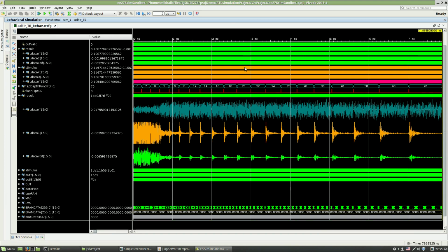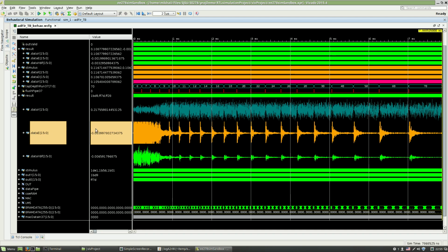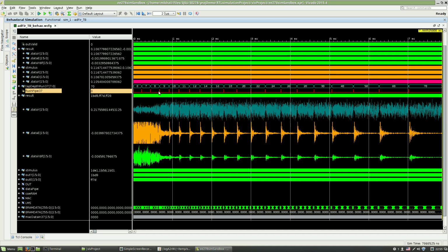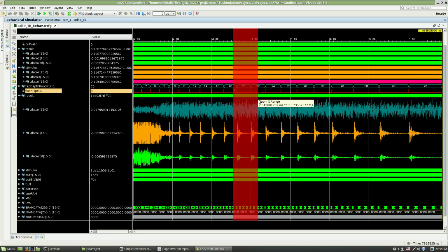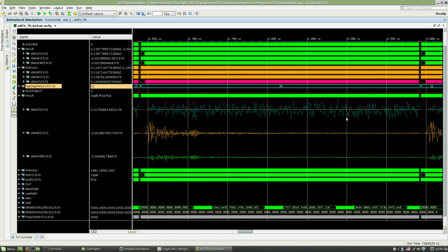The test bench presents a few top-level outputs as analog waveforms, particularly the filter output Y as a teal wave, the data error as an orange, and a difference from MATLAB model as green. Each of the red pulses you see on here shows a moment where the simulation is reset after each test run. So this right here is a single test run at tap depth of 20. As you can see, the waveform converges. Error converges to 0.